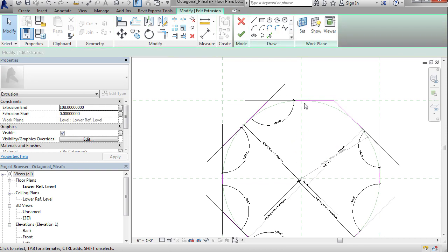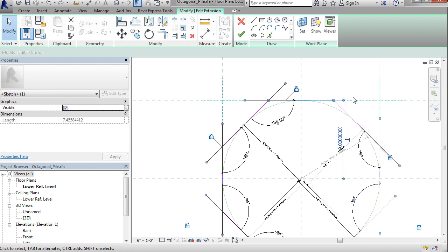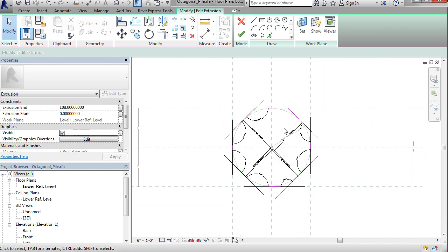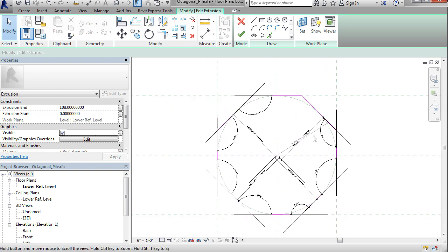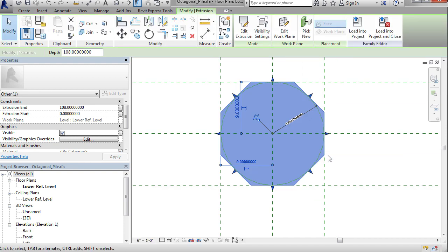For the other lines, the other sketch lines that landed on the existing reference planes, I simply aligned and locked them to that location. That way, as the family stretches, the ones that are horizontal or vertical on our screen go ahead and stretch with it. So hopefully this helps you see some of the mechanics behind the column family that I built for this particular lesson.